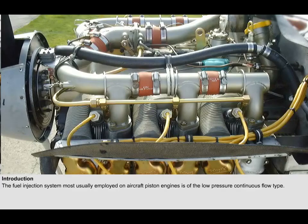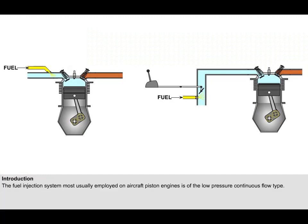In this lesson, we will look at the fuel injection systems which are used instead of carburetors on some aircraft piston engines. The injection system most usually employed is of the low-pressure continuous flow type. This system comes in two forms. Some fuel injection systems operate in a similar way to the carburetor by injecting fuel under pressure into the intake close to the throttle valve.